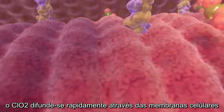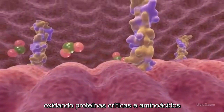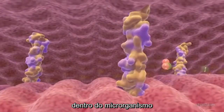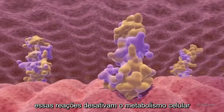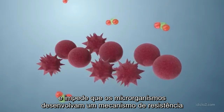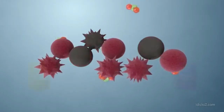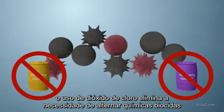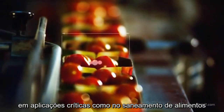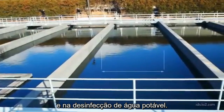ClO2 rapidly diffuses through cell membranes, oxidizing critical proteins and amino acids inside of the microorganism. These reactions disable cell metabolism and prevent microorganisms from developing a resistance mechanism. The use of chlorine dioxide eliminates the need to alternate biocidal chemistries in critical applications like food sanitation and drinking water disinfection.